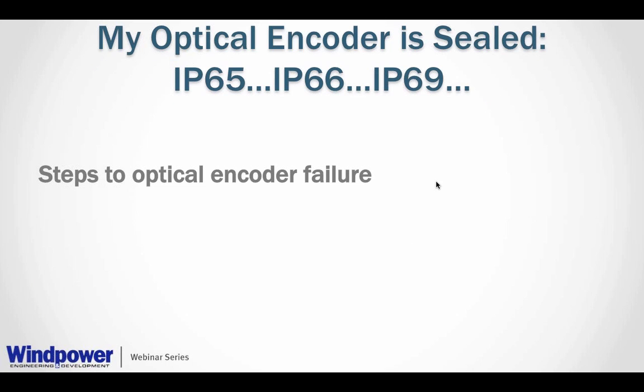So from the encoder world, traditionally, the defense was to argue, oh, I have better IP seals. I'll get a better IP-rated encoder. That's the key to the whole success of encoders, is to get a better IP rating. And so manufacturers really engaged in an arms race to increase the IP rating, the sealing rating of their encoders. But here's the truth. No matter what IP rating the manufacturer claims the encoder is the day they ship it to you, it changes, because you have rotating shafts, rotating seals, and those wear, just like a motor, just like any other application. And as those seals wear, the encoder can no longer withstand pressure changes that come from those temperature changes I warned you about.